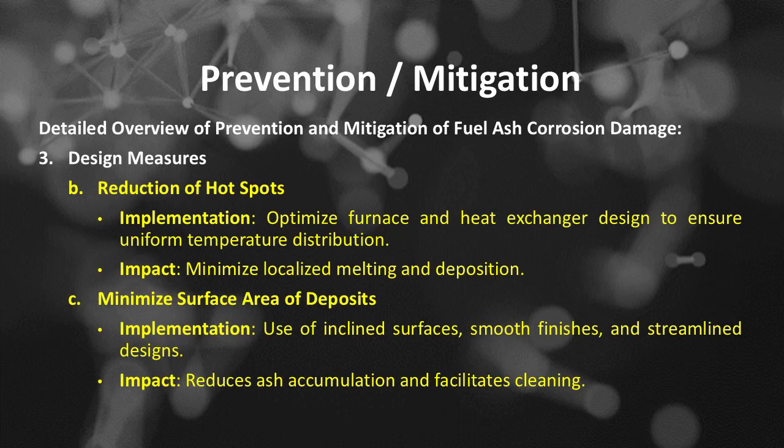Number B, reduction of hot spots. Implementation: optimize furnace and heat exchanger design to ensure uniform temperature distribution. Impact: minimize localized melting and deposition. Minimize surface area of deposits. Number C, implementation: use of inclined surfaces, smooth finishes, and streamlined designs. Impact: reduces ash accumulation and facilitates cleaning.